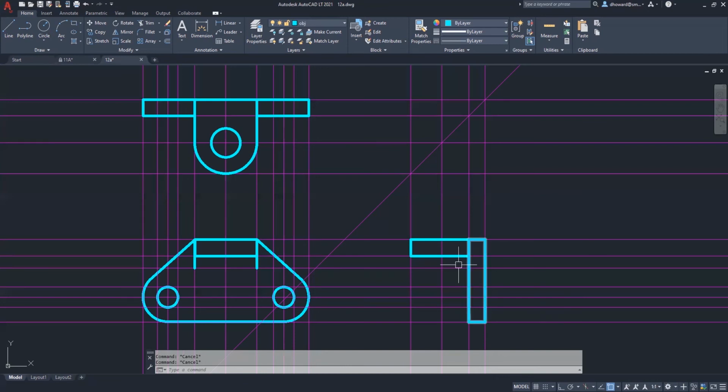And there is this radius I was talking about in here. So what would that look like? I just need to go to my fillet command right here, fillet, and type R, enter, and the radius is 3/8, and click this line and click that line.